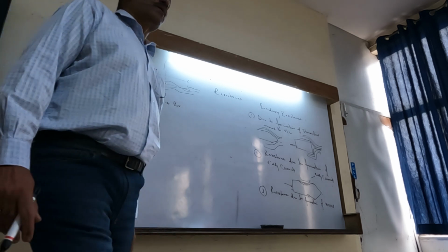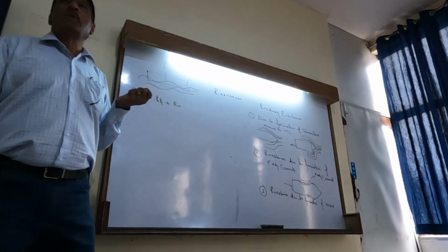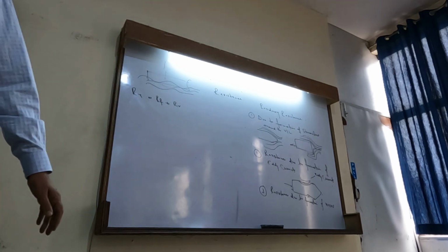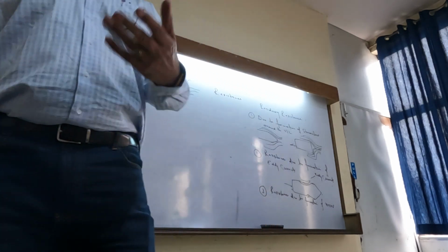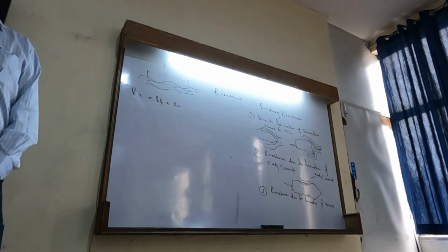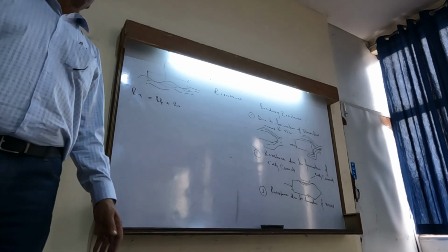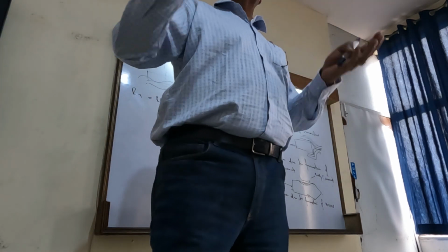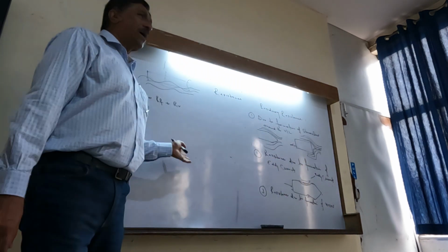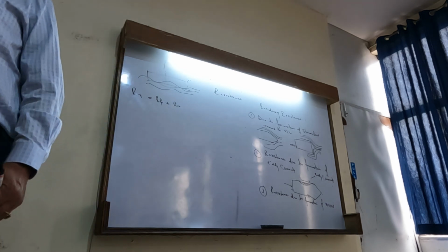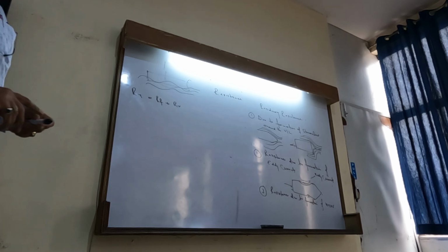Now, as I told you, for actual calculation for a particular vessel, this total resistance is the one which is calculated. This part of calculation is not in your scope, so I am not going into details of how it is done. But actually it is done by calculating frictional resistance and residual resistance for the prototype model, and then we have formulas of corresponding speeds and dimensions to calculate the total resistance of the vessel. However, we can calculate approximately the power required using what is known as admiralty coefficient. Under admiralty coefficient,